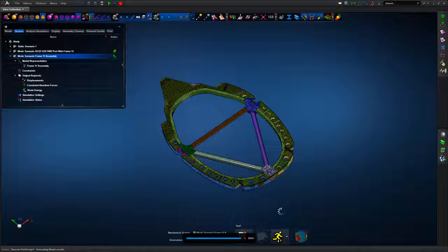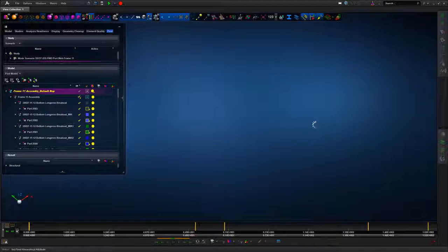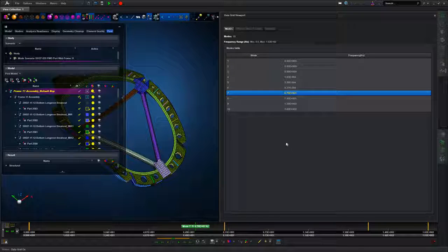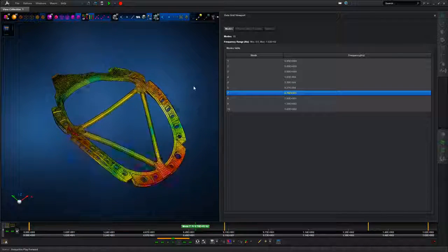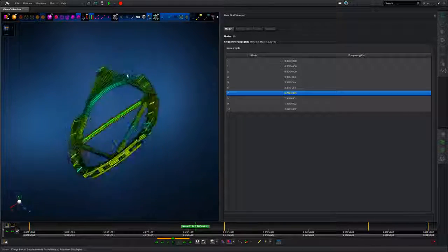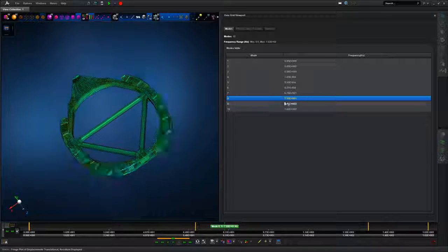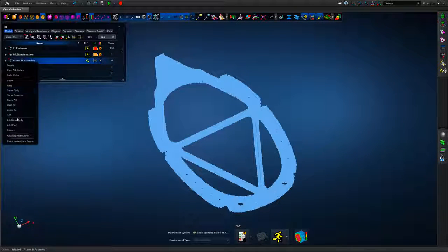So if we wanted to, we could go through each discrete part or sub-assembly and verify on their own basis, and then when we bring them together, the analysis time is far increased over a raw analysis, as it were. So again, looking at the elastic mode response, so mode 7 and above, so modes 1 to 6 are rigid body modes with very low frequencies, and looking at the mode 7 response, and again displacement, we can look at strain energy as well as a further check, but we're pretty happy with that definition. Everything's tied together, and the structure's moving with a clean definition as we'd expect.